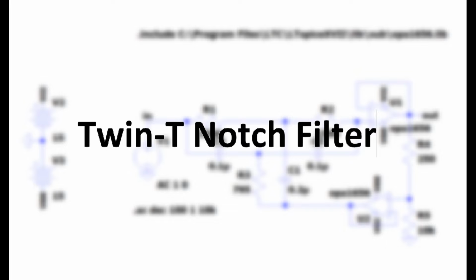So the band stop filter is basically a circuit which blocks a particular band of frequencies, a wide band or a mid band of frequencies, and it passes the rest of the frequencies in the spectrum. Whereas the notch filter is the advanced version of the band stop filter in which the bandwidth is narrow and it has a higher attenuation at a very narrow or steep notch of the frequency band or frequency spectrum.